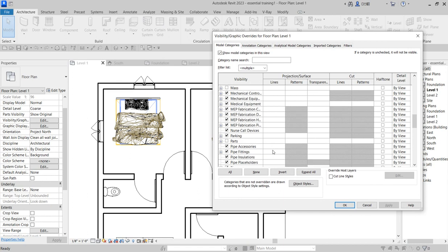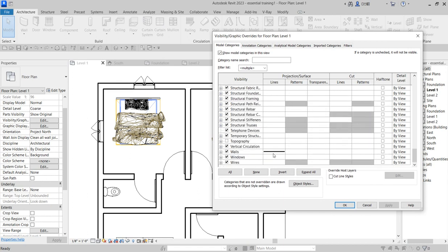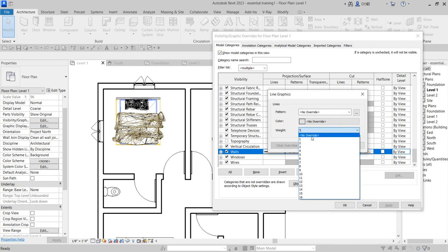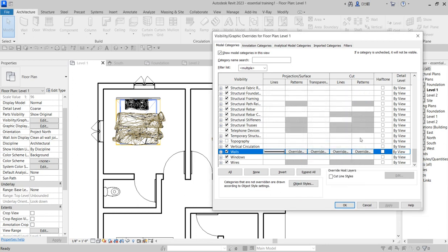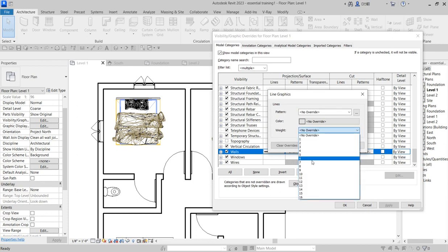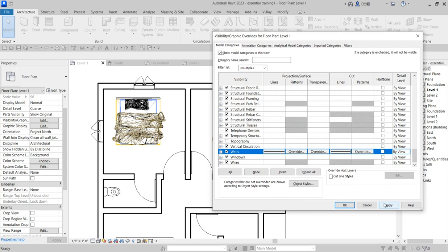Okay, now go down. You can click back again, just click override again. Click override here as well. Check this. Now you come to cut pattern. So you say line, first pattern, you say width and you change it to 6. Say okay, click apply, and look at it.